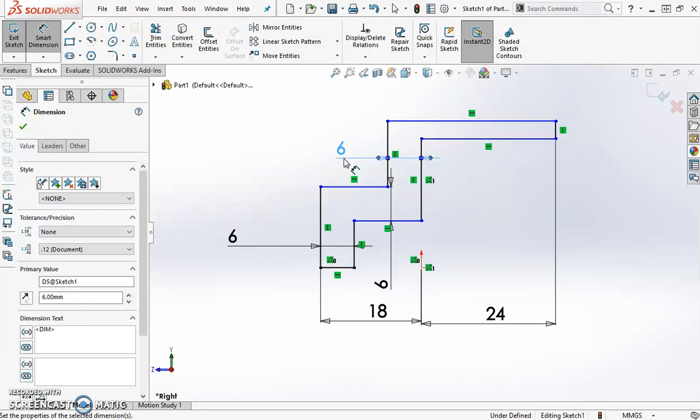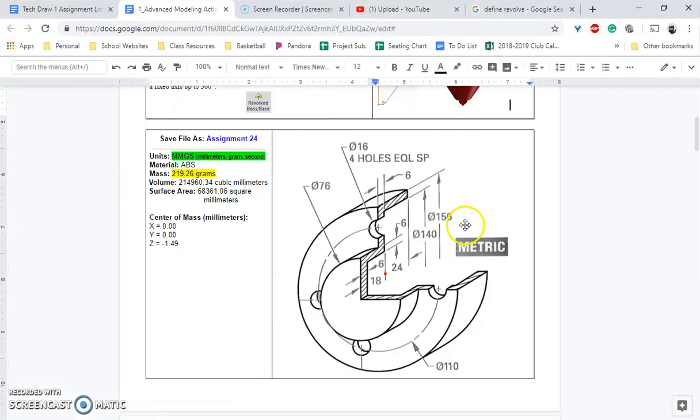Now, the next part confuses people. So I'm going to pull this back over to my screen. The lines that we have in blue are the horizontal lines, so these two and these two. Well, the distance from our origin to those lines is not defined real clearly here. But what it actually is, since this is a solid shape when it's finished, is our diameters. But it's half the diameter, because keep in mind, you're only drawing half of this shape. It's going to revolve around and have that same shape at the bottom.